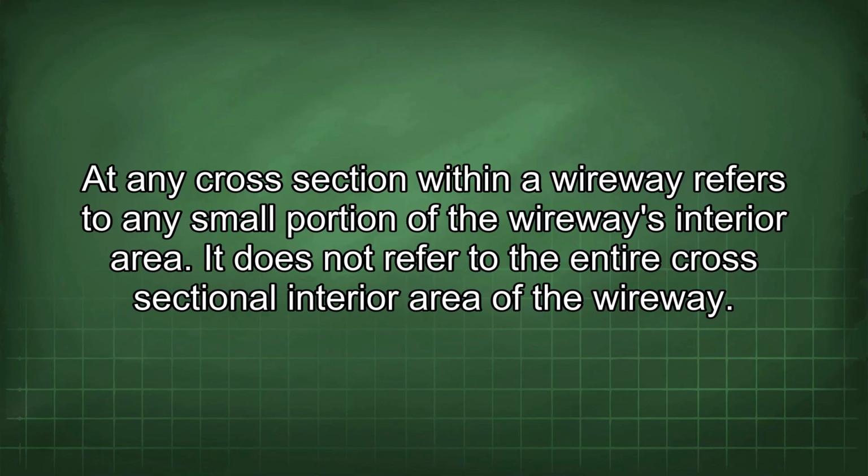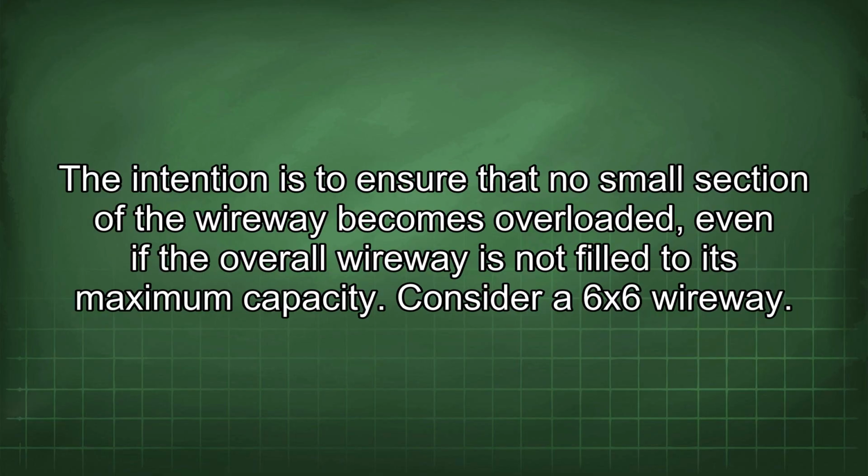At any cross-section within a wireway refers to any small portion of the wireway's interior area. It does not refer to the entire cross-sectional interior area of the wireway. The intention is to ensure that no small section of the wireway becomes overloaded, even if the overall wireway is not filled to its maximum capacity.